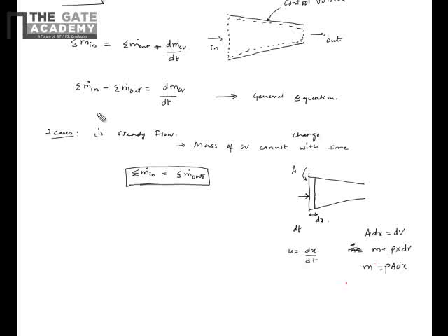Now the mass flow rate will be that mass divided by the time in which it enters. So this dx has been traveled in time dt. Now dx/dt is u, the normal velocity, so the mass flow rate is rho A u. This is the general expression for the mass flow rate going through a section of cross section A. Most of the time we write A u as Q, which is the volume flow rate. So if you have many inlets, you have many rho Qs.